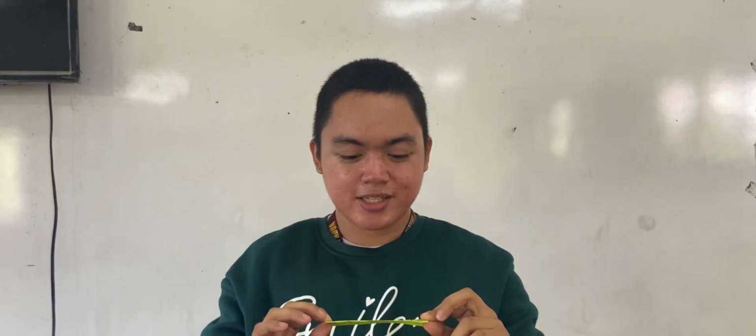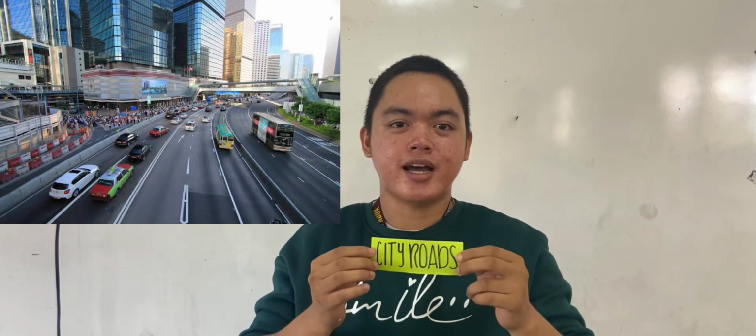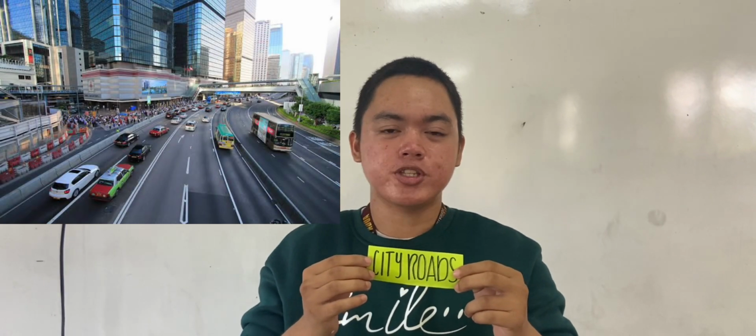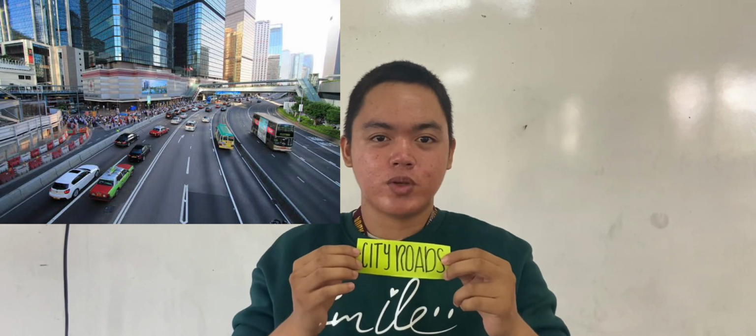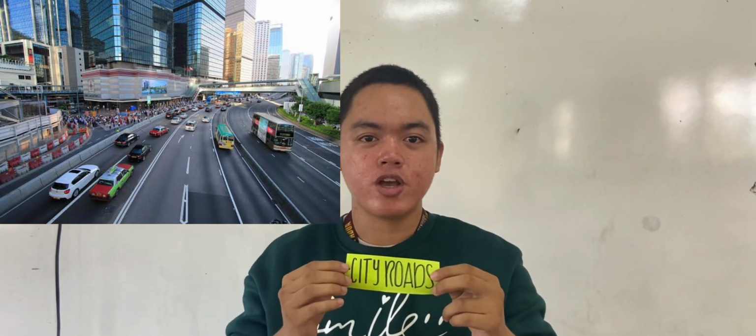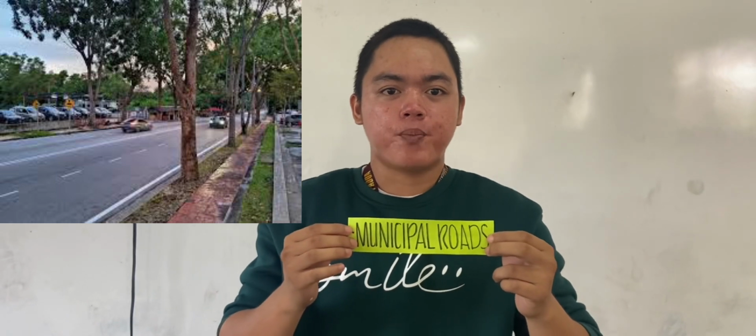Third, the city road. The interlink between municipalities within the city with the right of way of 15 meters. The fourth one, the municipal road. All roads within the town proper with the right of way of at least 10 meters. Barangay road, farm to market, with the right of way of less than 2 meters.